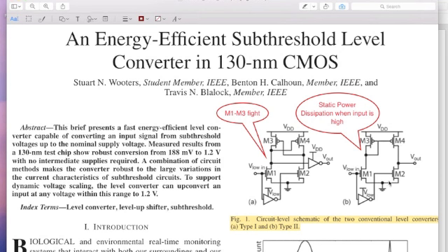So you have M4 and M2 basically off. Now when input goes high, the M3 is not fully on, unlike in this case. In this case, the M3 is fully on because the gate of the M3 is at ground, whereas here the gate of the M3 is close to VDD. If you give enough time, it will reach VDD or very close to VDD, otherwise it will be about a threshold below VDD.